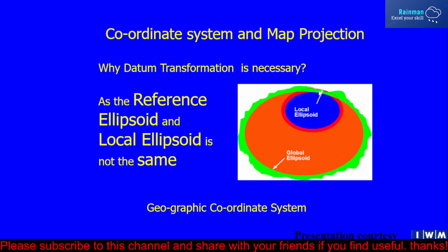See, I will do a survey for this area on the globe, and I want to develop a new coordinate system. Then consider an ellipsoid that fits here. So you can consider a new ellipsoid for your area, your coordinate system, and your mapping will be more accurate. Then you need the datum shifting also if you consider a local ellipsoid.